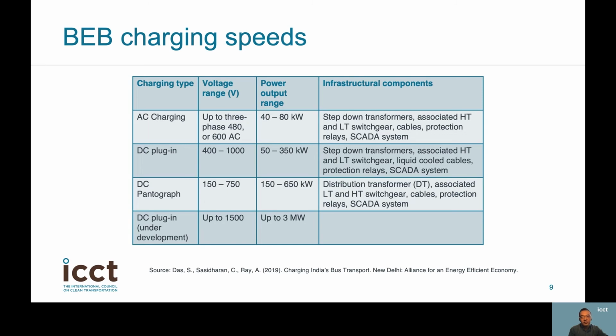Different physical interfaces mean different charging speeds. For AC charging, the capacity of the onboard charger and the AC power supply limit the capacity of AC charging. Lower power AC chargers, 20 kilowatts for example, are normally used for overnight depot charging to fully charge a battery in 10 hours, while faster chargers and connectors operating on three-phase industrial power supply like SAE J3068 enable quicker charging times thanks to the higher power output.